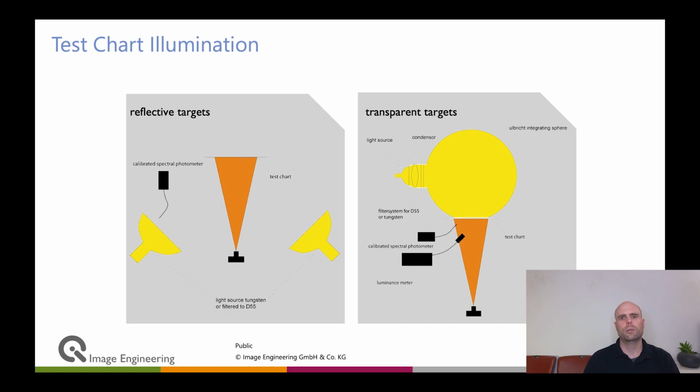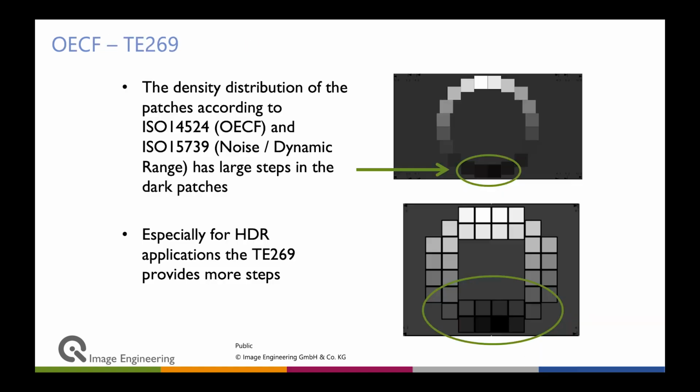For today's cameras, in most cases, if you want to measure dynamic range and cover the entire range of OECF, so how the camera reproduces luminances, you need a transmissive test target, and you need a powerful or good performance light source behind that is uniform, stable. For example, the LE7 of Image Engineering with IQ-LED technology, or an LG3, so high quality light sources.